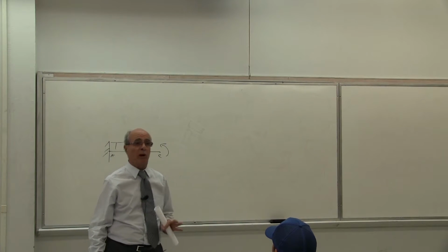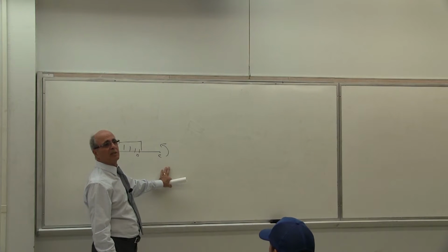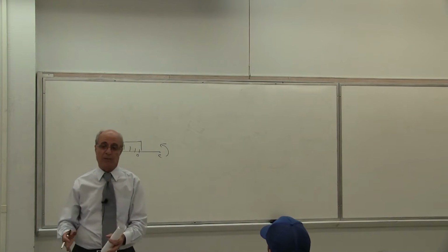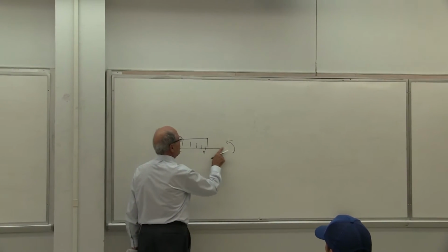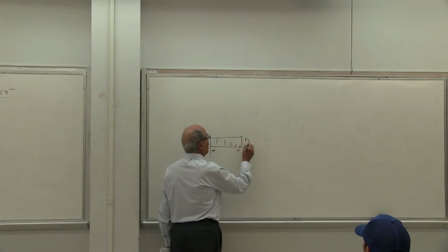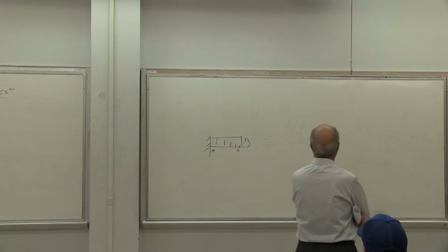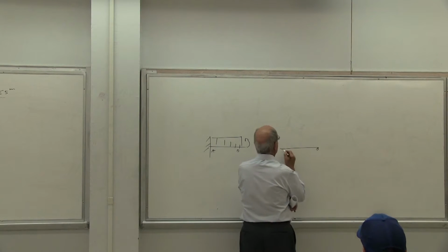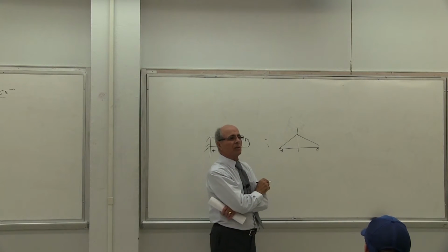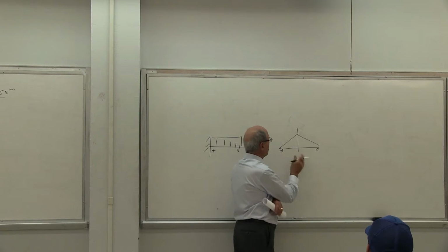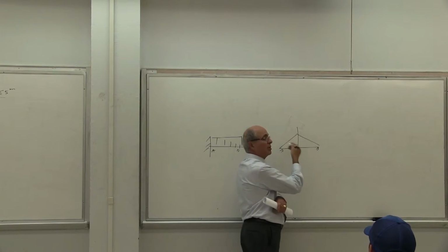because no question was asked about C. If you want to find the deflection under C, then you have to do AB and BC. Since the question was at the beginning of the homework set, they did not ask you to do anything about C. So you could bring this one here and treat it as one beam, which you did. There was another problem where the load was symmetrical, yes or no? If it is symmetrical, then you don't have to do it between the two spans, because it's symmetrical, so you only set it up with half.